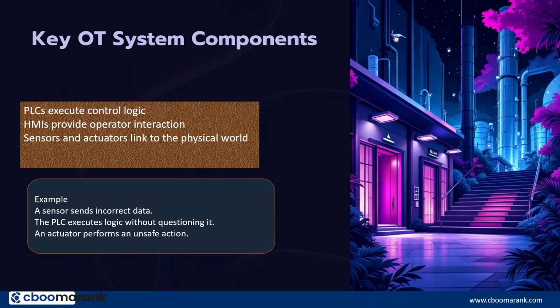A sensor sends incorrect data, whether due to failure or attack. Then the PLC does not question the data and simply executes the logic as designed. The result is unsafe physical behavior, and an actuator performs an unsafe action. This is why OT cybersecurity emphasizes input validation, segmentation, and defense in depth.